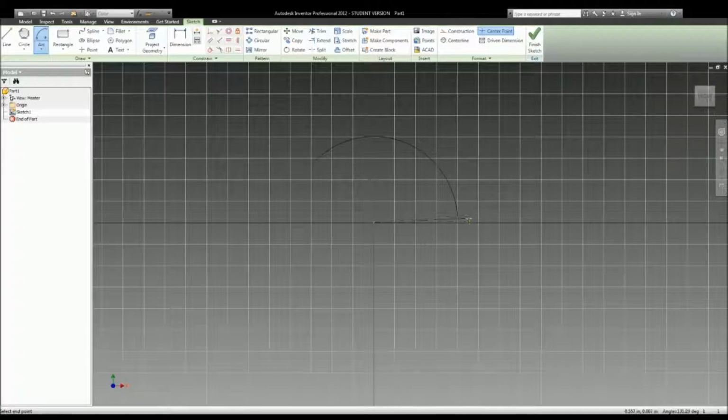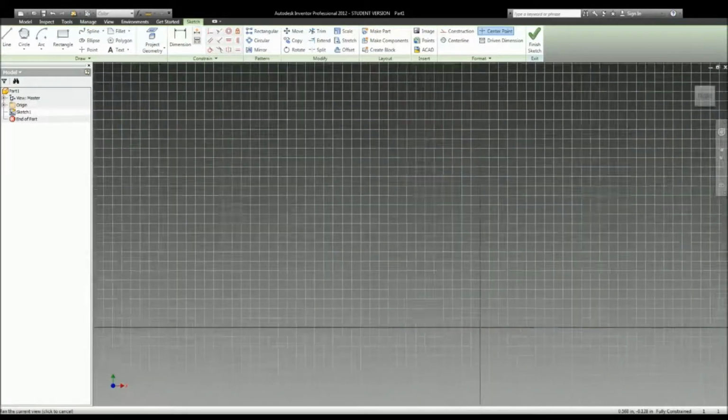So I'm going to go ahead and just bring it back to 0 by going 137 again, and voila, that is the arc that I specified at half inch, starting at 137 degrees and goes back to 0. Oops, did not mean to do that.